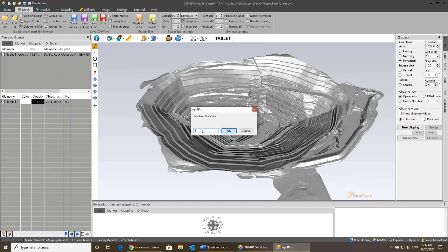What it means is internally, if you say 5 iterations, it will take that algorithm for simplification, run it 5 times, and then give you an output. So if you say 5 or you say 50, the output would look very different from those two functions. So just be careful on your number of iterations. I'm not going to do it because it's not going to work well for this particular scenario.